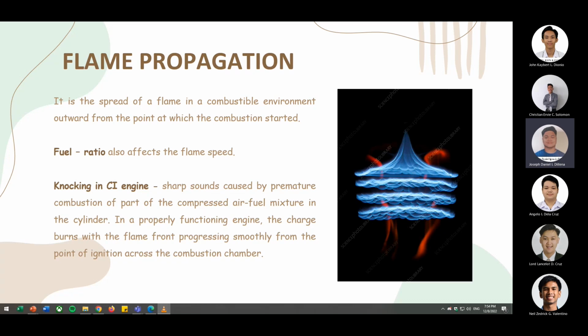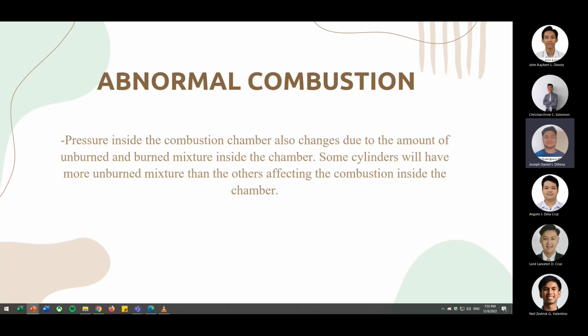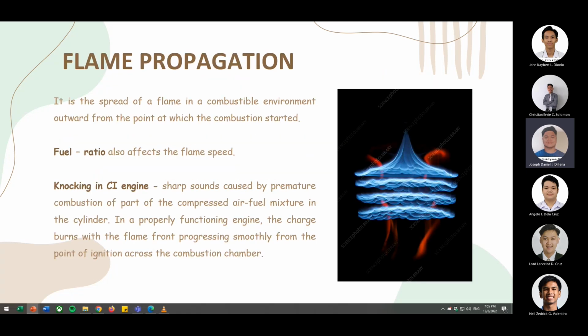Higher flame speed is produced by spinning of the tiny particles. When the incoming mixture develops momentum, turbulence is produced. Fuel ratio also affects the flame speed. If the mixture is rich, then combustion will be shorter. A leaner mixture will take more time to combust, since the fuel particles are fewer in this case. However, having a rich mixture beyond a limit will result in incomplete combustion.